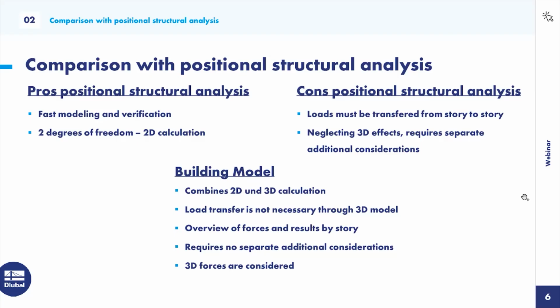Okay, another con is that this 2D calculation neglects 3D effects, and for example some forces, let's say torsional moments, and you also need separate additional considerations or additional checks for the whole building. And now to the building model.